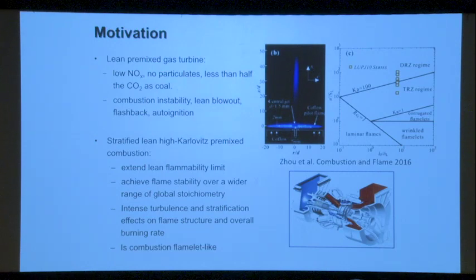and autoignition. And so the case that we looked at was a stratified lean methane air premixed flame at very intense turbulence conditions, or so-called high Karlovitz conditions, where the turbulence Reynolds numbers are relatively high, and there's strong overlap between the turbulence timescales and flame timescales.